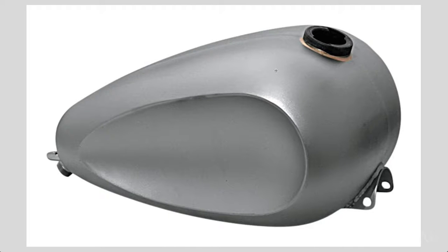So this fuel tank would be a very good example of an object that would benefit from this very low poly approach to curvature. This is obviously a very smooth curved surface, and to establish this we would really want to keep our geometry to a minimum. Now we also have this indented feature here, so the edge flow around this detail is probably the most important thing we have to consider in this object.